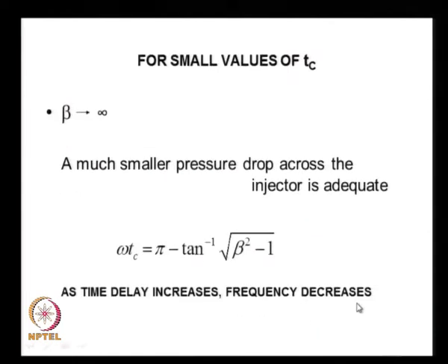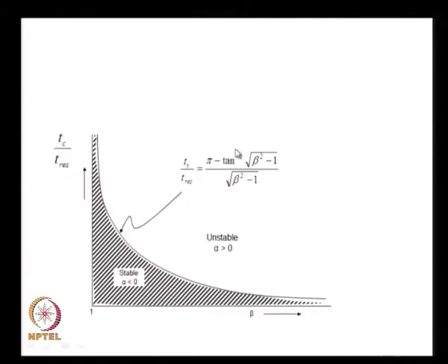And this I follow up, and now I say if the value of Tc is not infinity, then what happens to the value of beta? You go back, yes, this is for infinity when beta is equal to 1. When Tc has a finite value and keeps on decreasing, the value of beta keeps increasing.